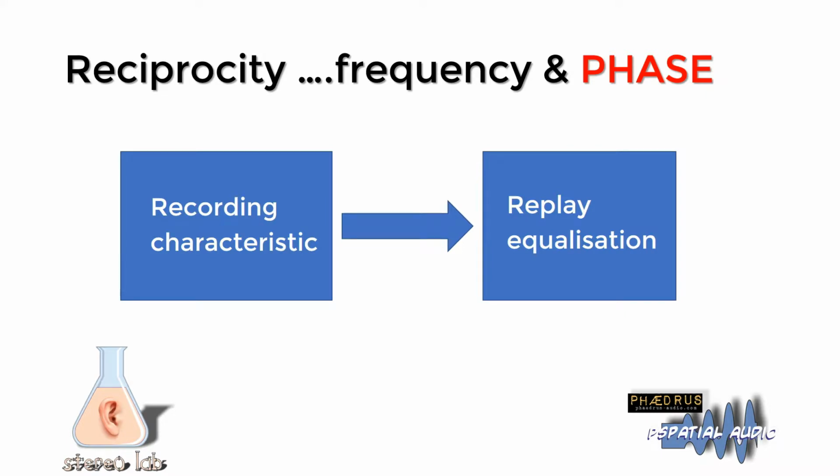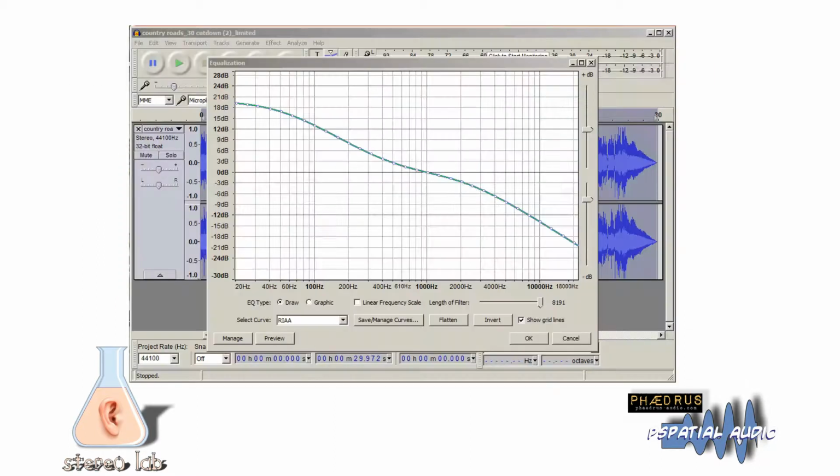And importantly, the correction curves in Stereolab are not derived from FFT curve filtering. Such a technique results in generation of non-causal linear phase filters, which do not correctly compensate for the phase distortion introduced in the preemphasis filter. Unfortunately, this is the technique employed in most of the software solutions commercially available. Not only does this technique result in frequency response anomalies, we've measured around 1 dB errors, but much more seriously it destroys the linear phase response of the preemphasis-deemphasis chain.